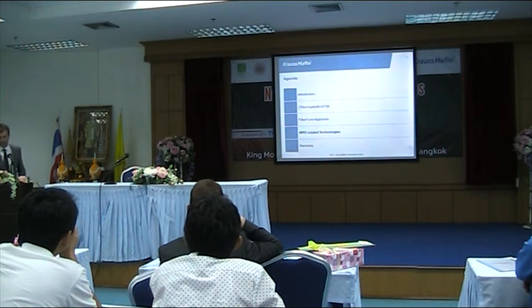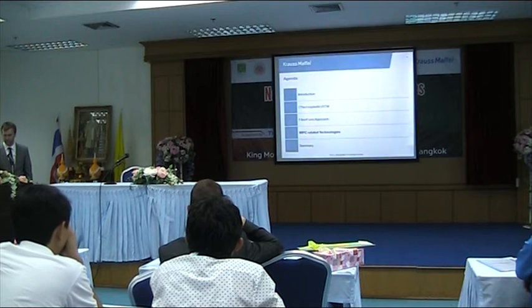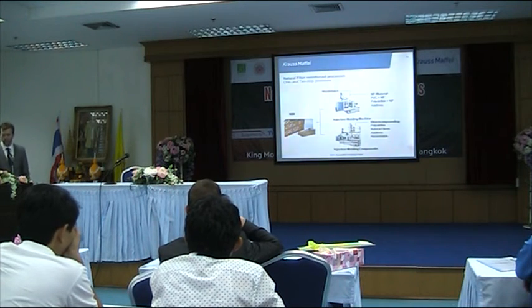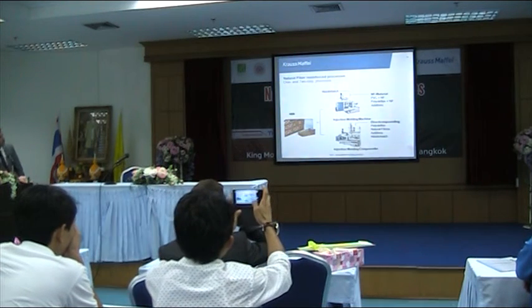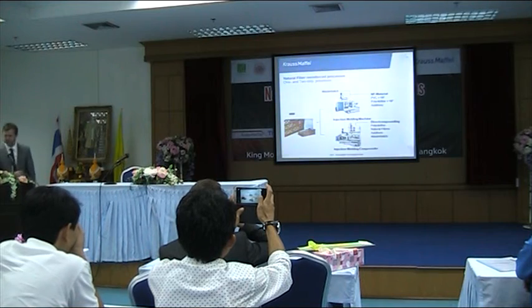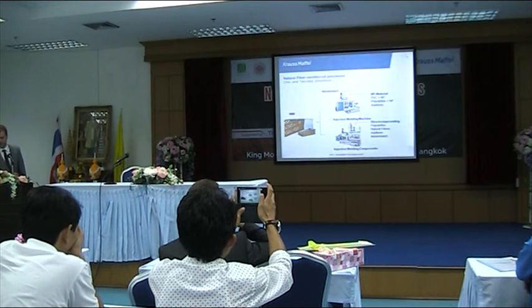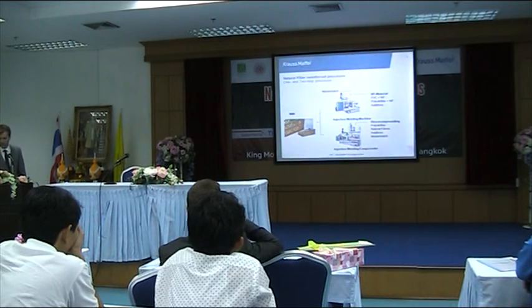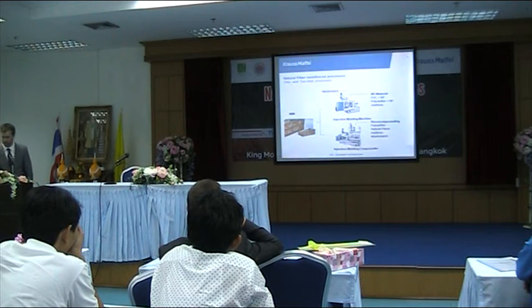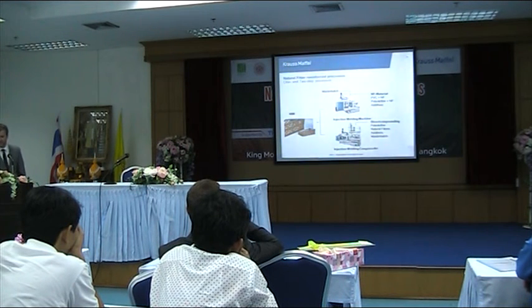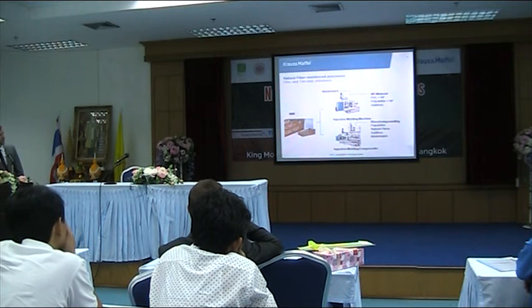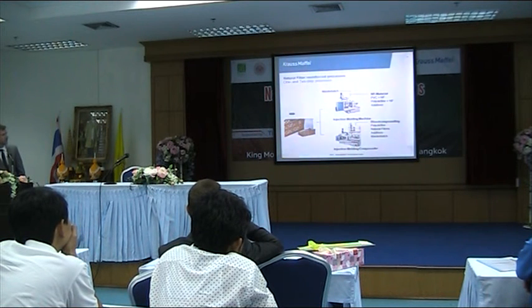So now some wood plastic composite related technologies. You can make two approaches. The first one is using a standard machine. So you use the natural fiber material, for example PVC and natural fiber, or polyolefin and natural fiber, some additives and masterbatch, and you can produce several product applications with a standard machine. And the second approach is the injection molding compounder.